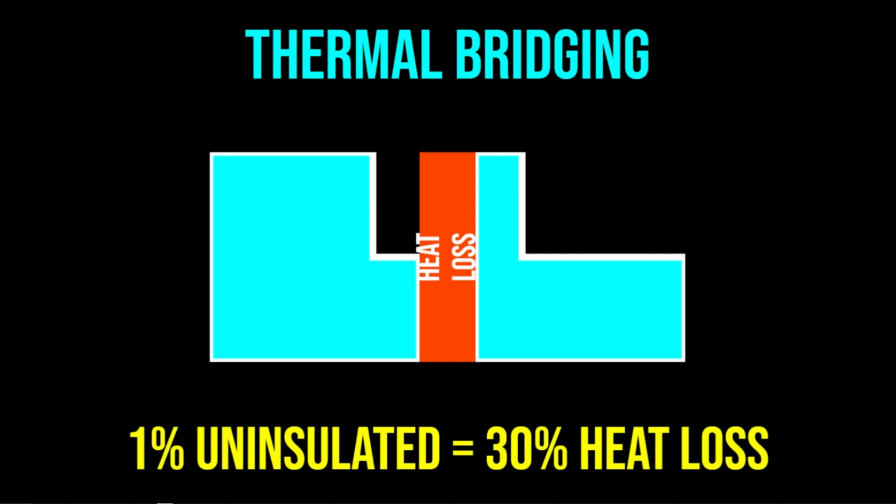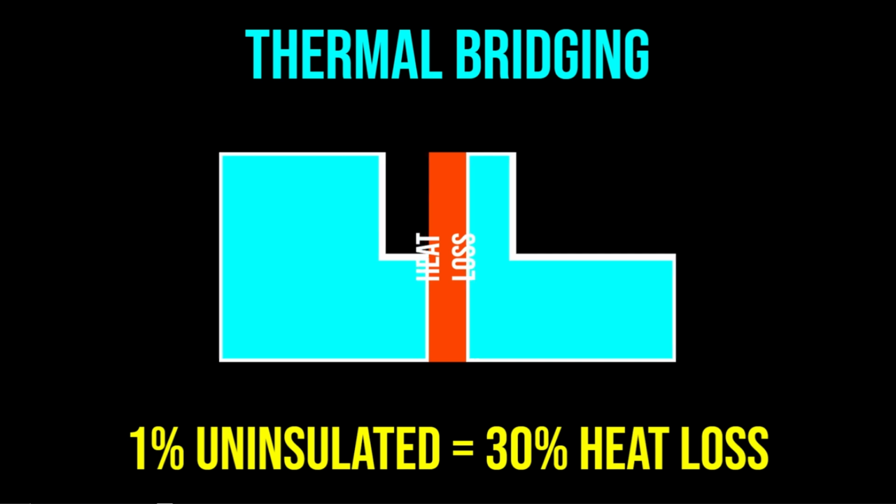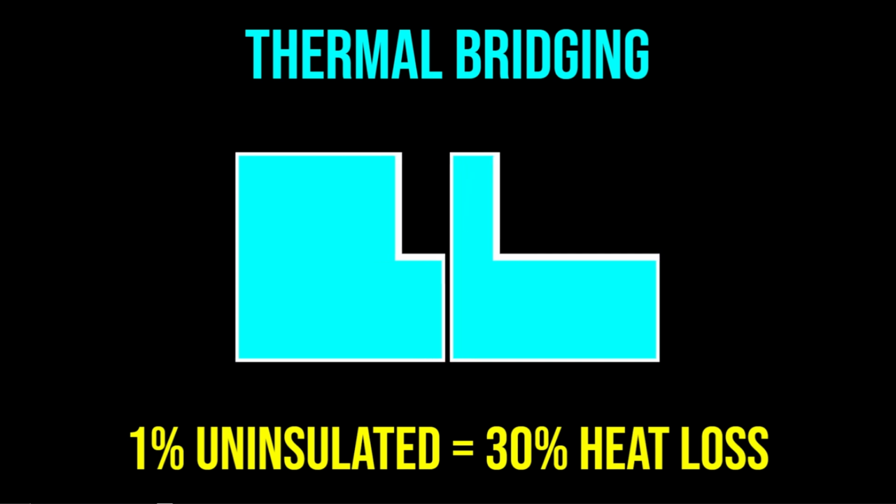Thermal bridging occurs where gaps between boards or structural penetrations allow heat to bypass the insulation layer. Rigid boards like EPS and XPS require precise cutting and are often manufactured with shiplap or tongue-and-groove edges to ensure a continuous thermal envelope. Any gaps larger than a few millimeters should be filled with expanding foam to prevent convective heat loss. Mineral wool, being flexible, can be friction-fitted between studs, filling voids more effectively in irregular spaces.